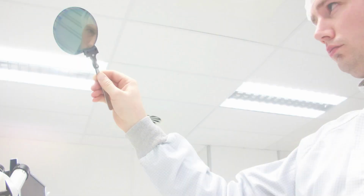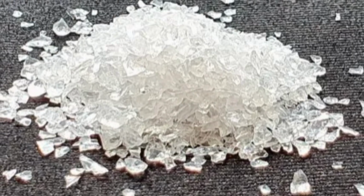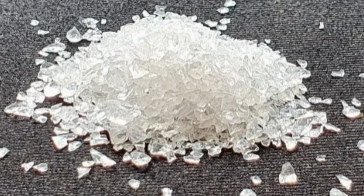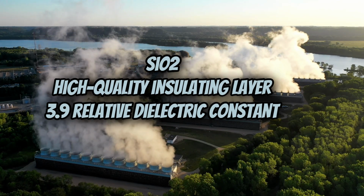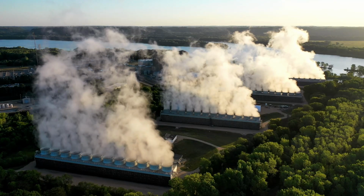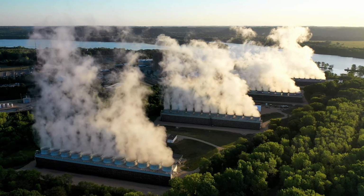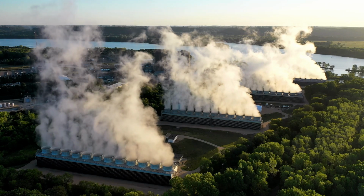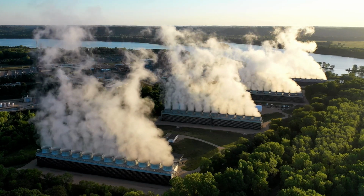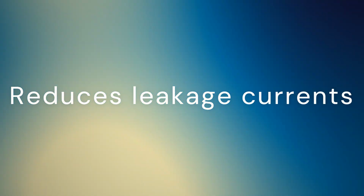But the biggest advantage of silicon is its ability to form silicon dioxide, SiO2, directly on its surface through simple thermal oxidation, a high quality insulating layer with a 3.9 relative dielectric constant. This natural formation of the gate oxide in MOSFETs eliminated the need for expensive and complex deposition techniques in the early days of IC manufacturing. SiO2 is also extremely stable, provides excellent electrical isolation, and helps reduce leakage currents.